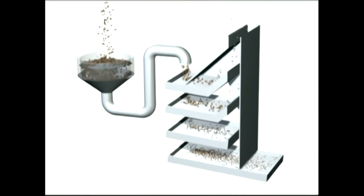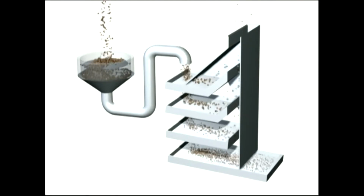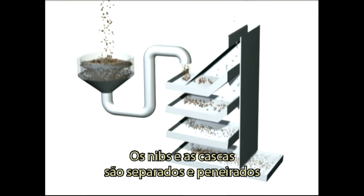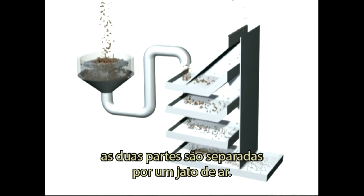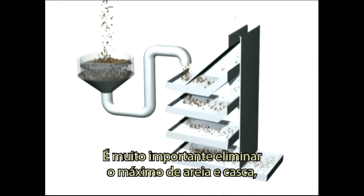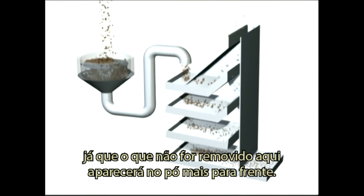In order to separate the nib from the shell, the beans are broken mechanically. The blend of nibs and shell will be sorted and sifted by a series of machines. As the shell is lighter, the two are separated by an air stream. It's very important to take out most of the sand and shells, as what is not removed here will show up later in the powder.